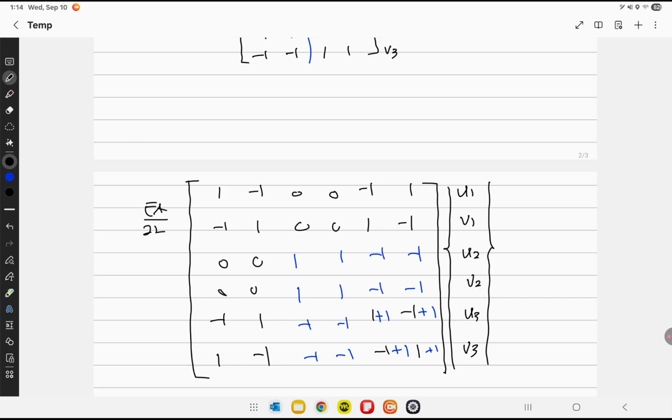Easier version. A lot of times the name, the words, tell what we need to do. Like the assembly, that tells what we need to do, right? What is the next step to apply the boundary condition? How do you actually apply the boundary condition? You cross off the rows and columns in the matrix that correspond to U1, V1, U3, V3, as well as F1 and F3. So that's what the book says, the process. I guess nobody read the book, right? There are specific words that I highlighted in bold typeface in the book.